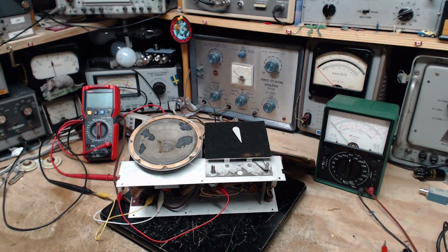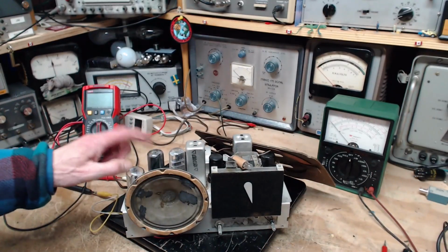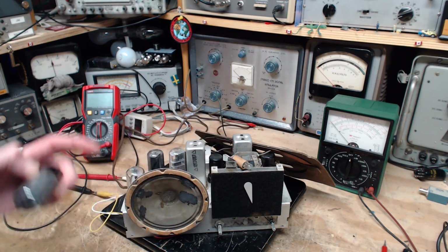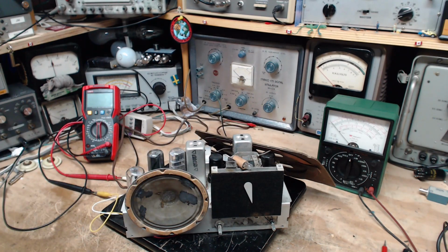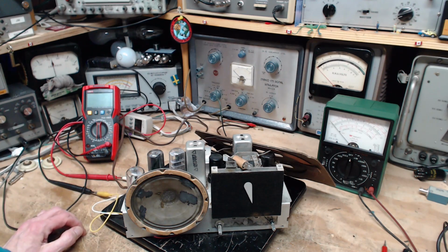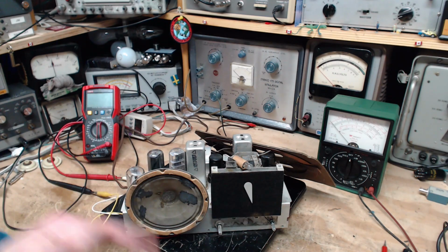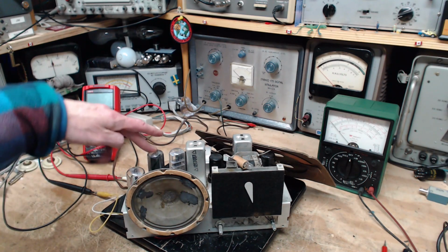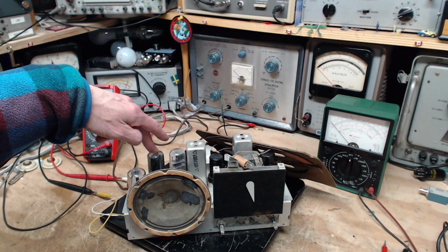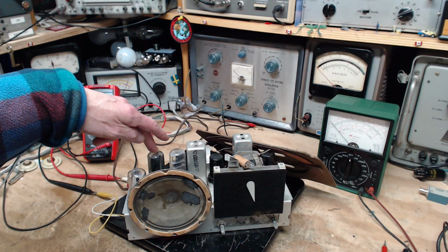I'm going to start out by talking a bit about the odd experiences I had with this radio yesterday and this output tube. This is the original output tube. This is a replacement here. So what I did was the standard thing, check the grid to see if it's positive. Oh, a little bit positive. Change the blocking capacitor to stop the leak and stop the positivity on the grid of the output tube. But when I changed the capacitor, there's still some positive voltage sitting on the grid.